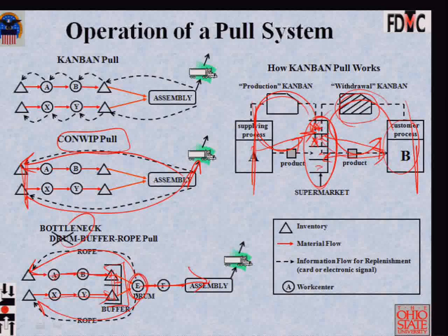So again, in a true job shop, the pull concept would simply be you take a set of orders, you sort them by due date, you do a simulated or what is called a soft release of those orders into the system. The finite capacity scheduling system will tell you which orders can be processed and which orders will end up in queue at certain constraint work centers. Then you make a decision whether or not to allow some of those orders to be released if you know that they will end up in queue at the constraint work centers. So again, I'm a big fan of finite capacity scheduling for job shops, and I don't believe that any of these much touted systems correctly capture the nuances of the job shop.